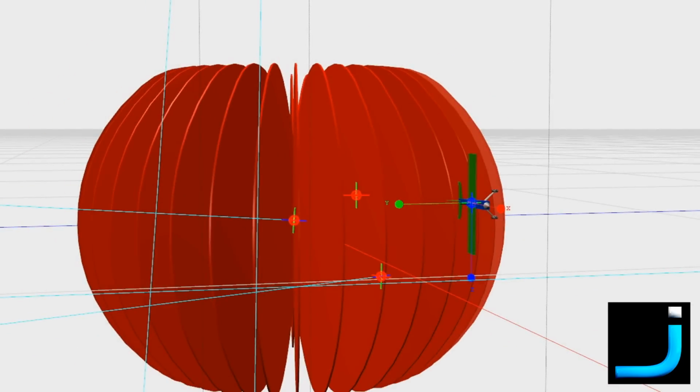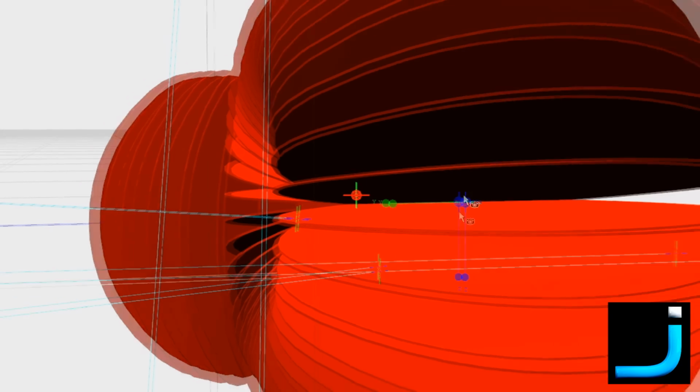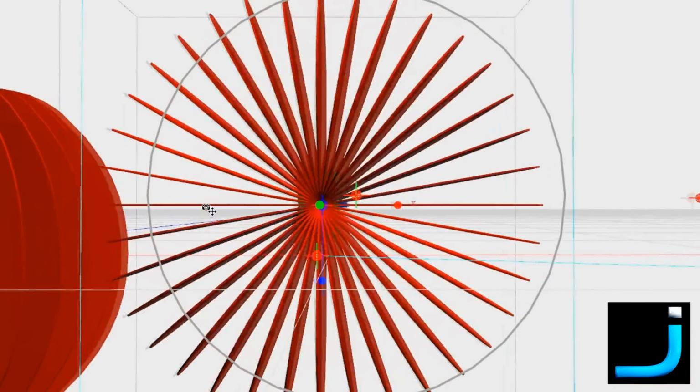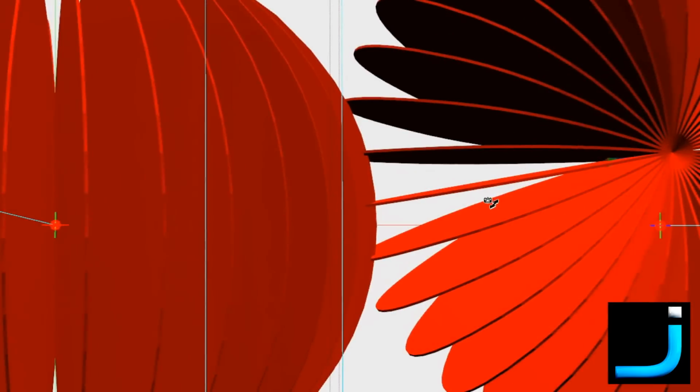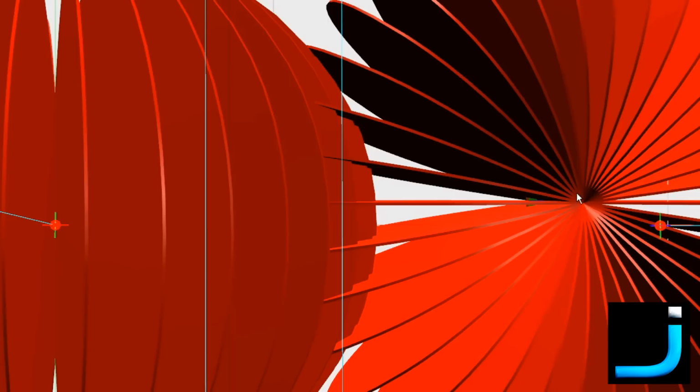Now, as a result of that, so is our signal. We'll switch back to the front view. There's our plane in a hard turn. Now, just because our plane is in range doesn't mean we're going to get a good signal, because we've got a mismatch of polarization here. One is vertically polarized, the ground station, but the plane is now horizontally polarized. So what it means is that we have a mismatch of polarization. This mismatch will cost us about 26 decibels of gain loss, which is significant, yeah?